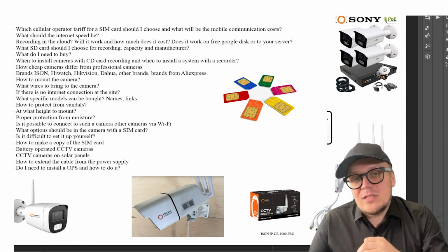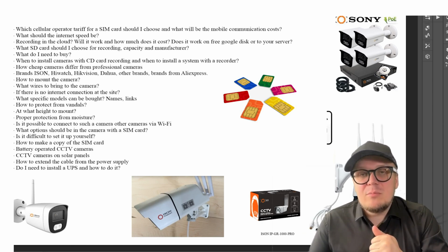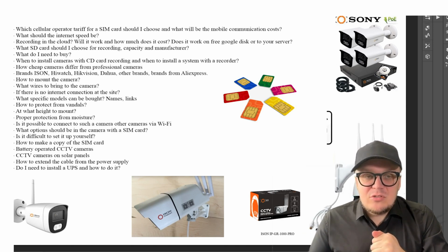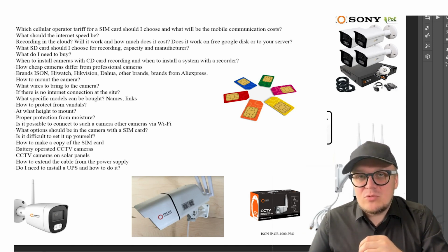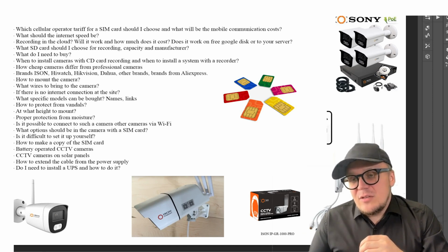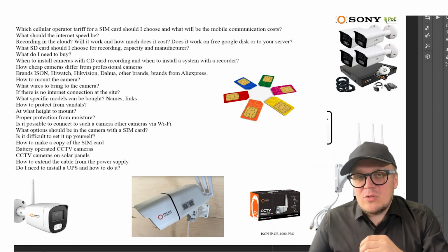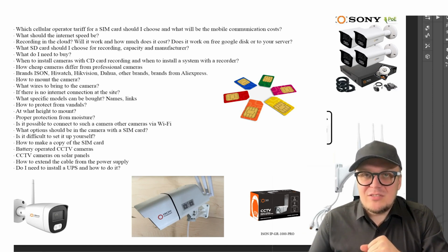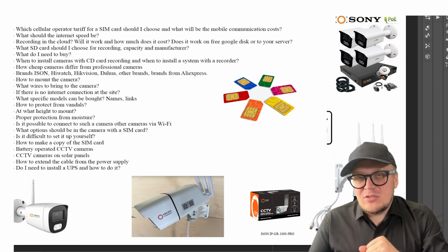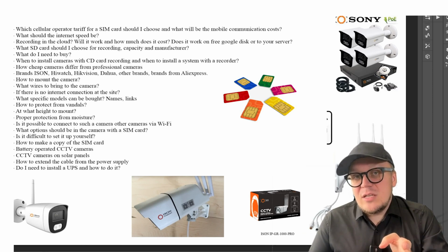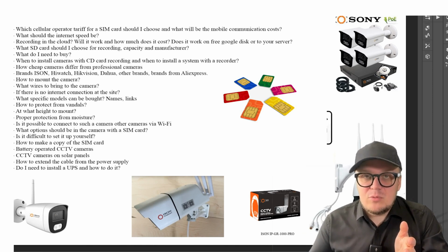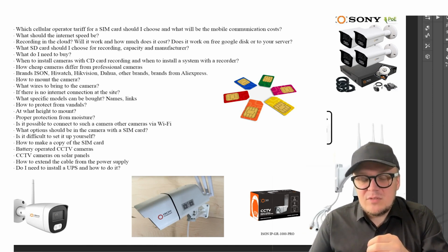Surveillance cameras with batteries. The common question is, if I have no power supply at my site, are there surveillance cameras with batteries? Currently, no professional surveillance equipment manufacturer makes surveillance cameras with batteries, because this is not serious surveillance. There are no batteries that can power your surveillance camera for at least 6 months. It's always the case that you need to change the battery once a week, essentially replacing the batteries in the camera itself. What kind of surveillance is it when you need to climb up a pole once a week and change the power supply in your surveillance camera? Therefore, professional equipment will always be powered only from the grid.